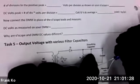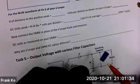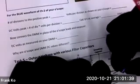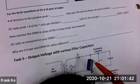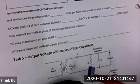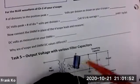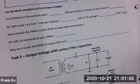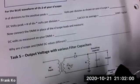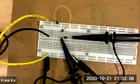On your electrolytics, can you also see that there is, maybe not on this particular one, but on some of them, okay, here's one. On some of the electrolytics, you will see that there's a white band. The white band indicates the negative lead that's attached to that side of the electrolytic capacitor, okay? And if it's not color banded with a white band showing negative, the shorter lead is going to be the negative lead. So we're going to connect it in this fashion.